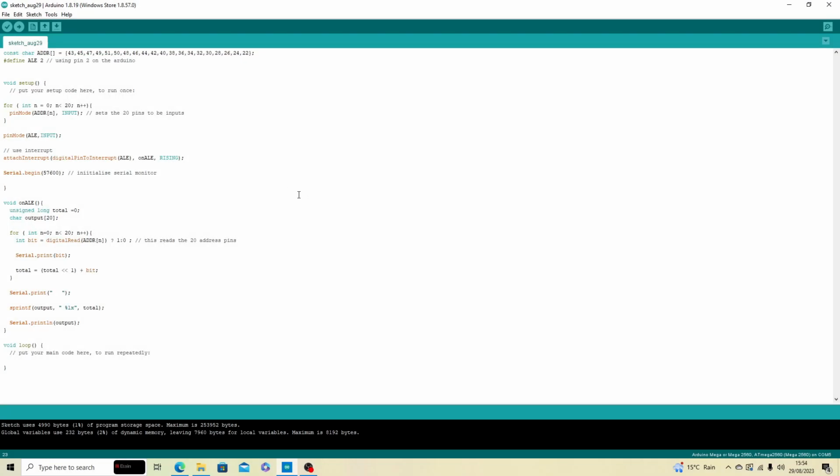Now the sketch is compiled. What we need to do now is upload that to the Arduino, power up the board and press the reset. So let's upload that. So here it's uploading, done uploading. So it's now uploaded to the little Arduino Mega. We can power on the board.